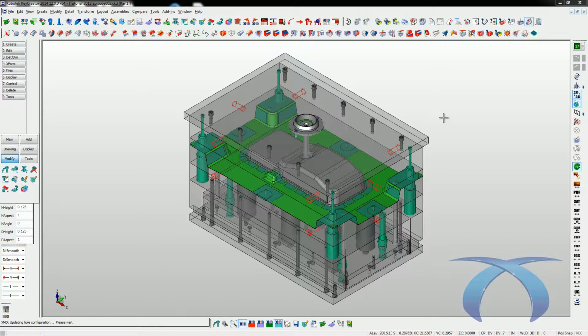So the first thing that we want to do is bring in true actual solids as our core and cavity blocks. One thing we can do with XMD is start and finish the design just as it is, even though we don't have a full solid and we have all our parting line and whatnot. But we also can swap in solids anytime we want, regardless of what level that solid is at, and we can always re-swap later as they get finished if we want. So by bringing in those solids, we can start utilizing XMD's features to their maximum potential.